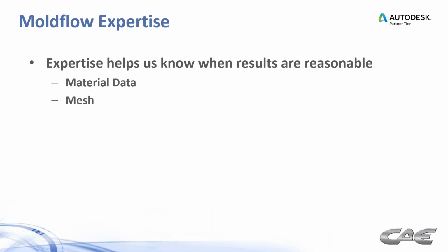We talked about material data. Haven't talked about mesh. Mesh is just creating a simulation model in Moldflow, and there's different ways to do it. And with each one of those ways, they are better used in certain cases than others, okay? Mid-plane versus dual domain versus 3D meshes all have their advantages and disadvantages. And it's important to know what cases for which each of these is most beneficial. Sometimes we use more than one type of mesh on the same project.